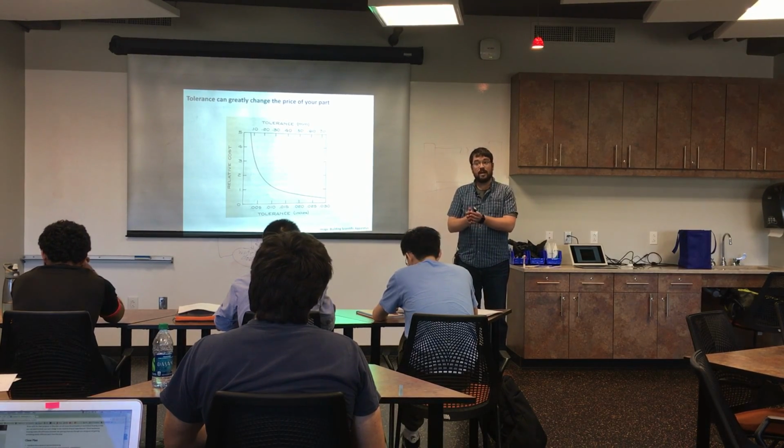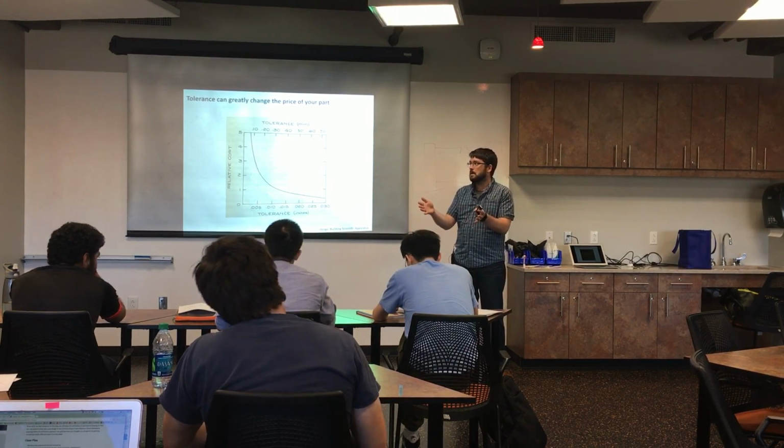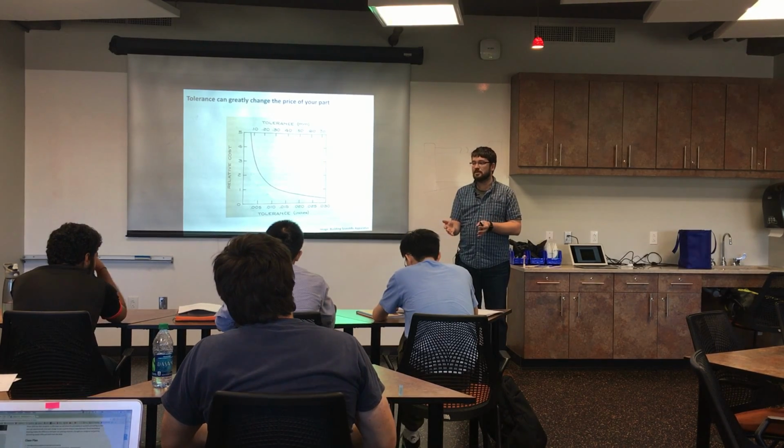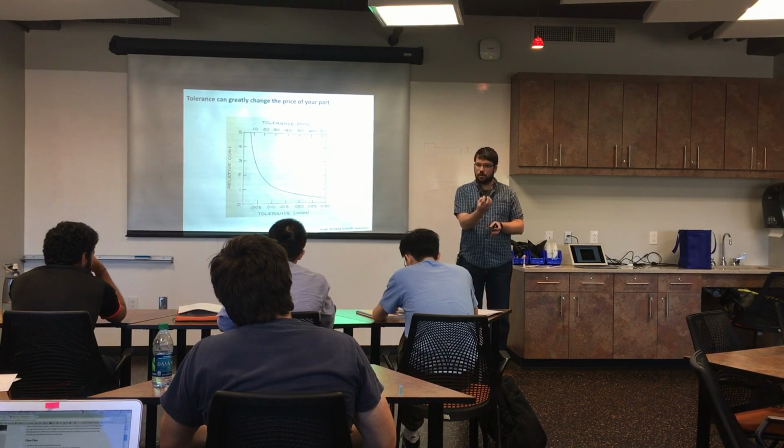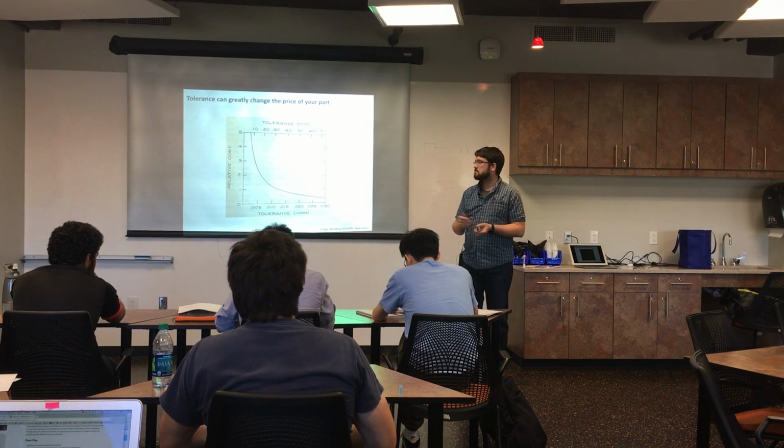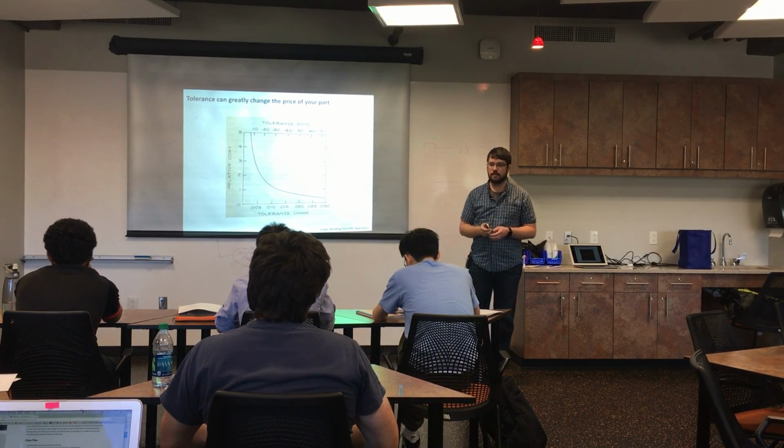So maybe it's okay if your block is even 100 thou over size in one direction, and just the holes in it need to be precisely dimensioned. You can save yourself a lot of money.